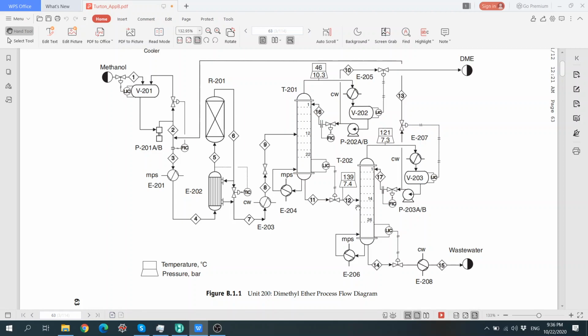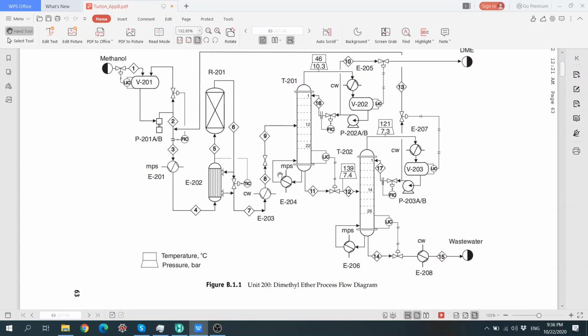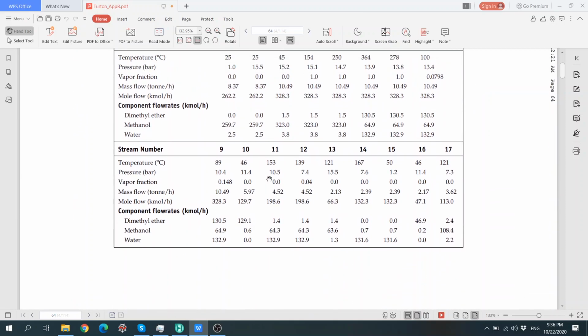I don't know if you still remember how to design a distillation column, Aisha and the others. Okay, so let's assume that we all don't know. The first thing we need to do, if we want to separate one component from the others, and in this case we have 3 components, is to base the separation system on the properties that make them different.